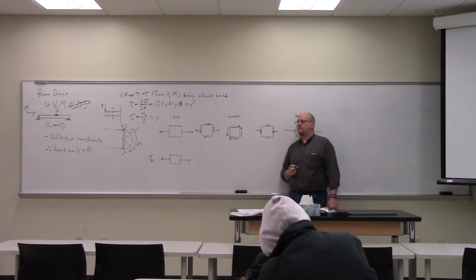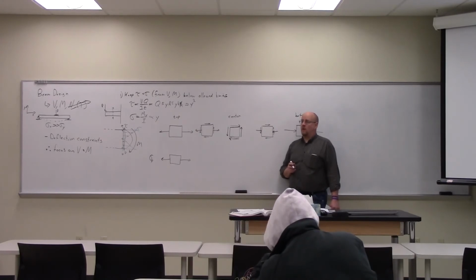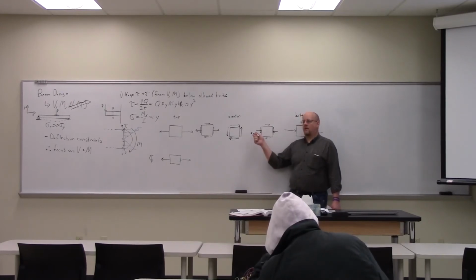It's just the same direction as it already is in the center? No, because in this orientation, what's my normal stress as it's drawn on the board? You don't have any normal stress. Right, 0. And my shear stress is something. Or think of it in terms of a Mohr circle. Where am I on the Mohr circle? Up and down. Where do I go to get my principal stresses? 90 degrees? You just orient it 90 degrees? No, not 90, 45.